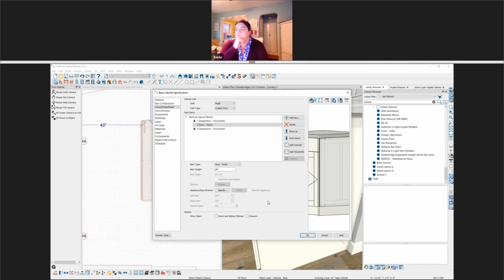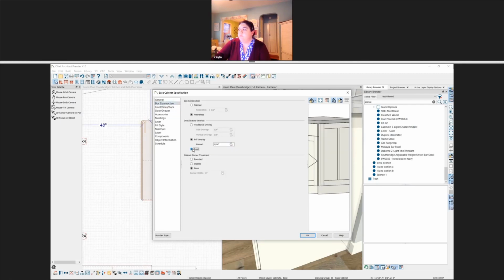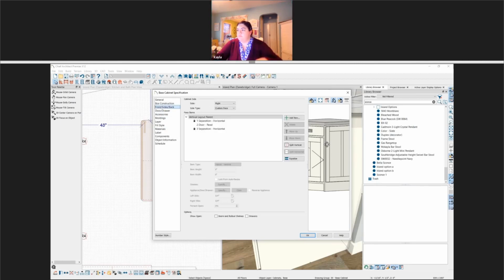But anyway, that's a way to at least get something that looks appropriate. And can you do that specifically if that box were inset? Would that door panel subsequently show as inset, which is what I'm trying to avoid? Yeah, if the whole thing is inset, then all of them are inset. So if you change that box to inset, then that door panel is going to look inset as well, and it's going to show the face frames and not as an integrated panel.